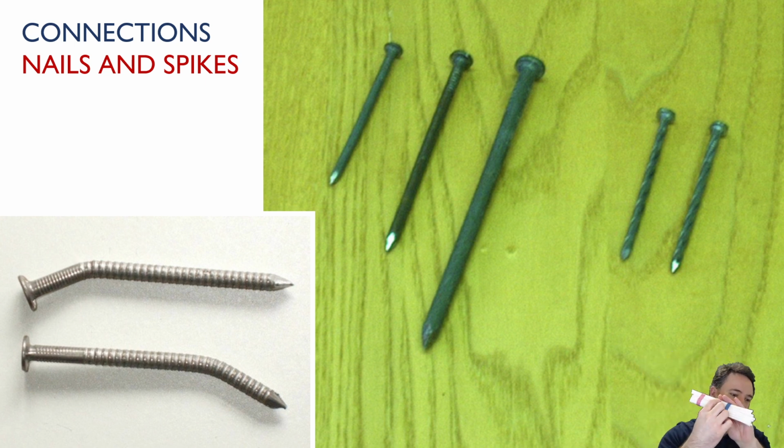The idea is the nail is going to push aside the wood fibers when I nail the nail in, and the friction is what keeps that nail in place, of course. Sometimes the profile of the nail, depending on what kind of nail you're using, might have a texture that helps with that friction. But the primary way that we load nails is not a pull out like this, but instead shear connections like this, where I have something pulling on the member and the nail is held in place by friction for vertical lateral loads.